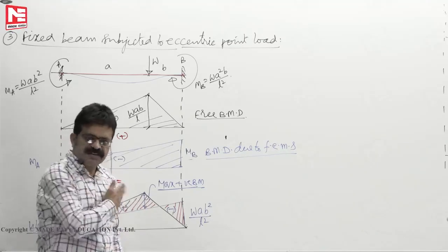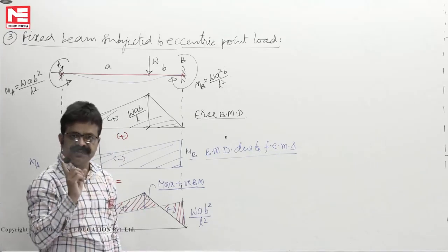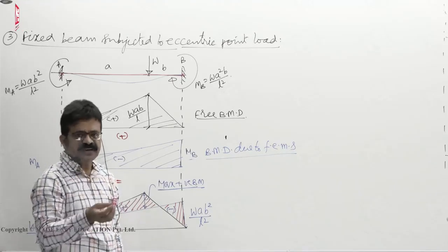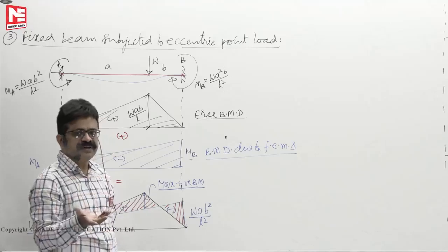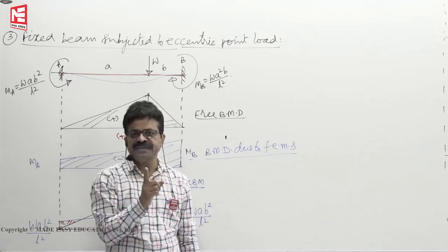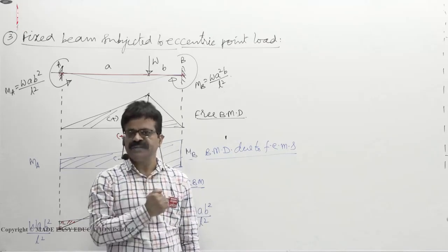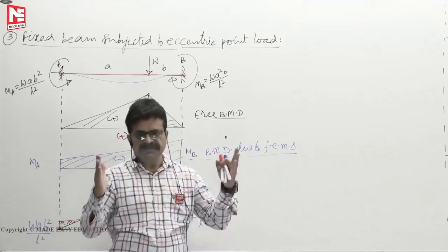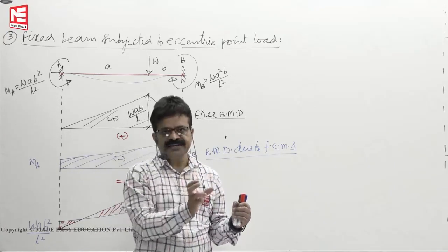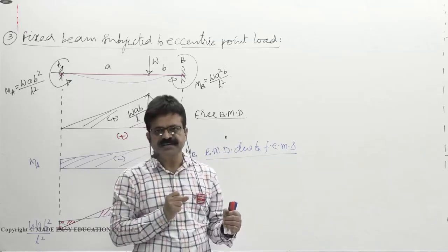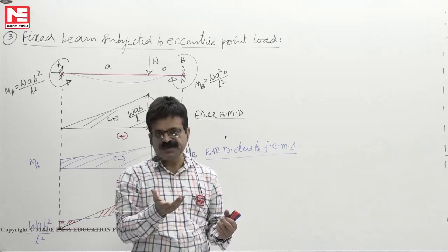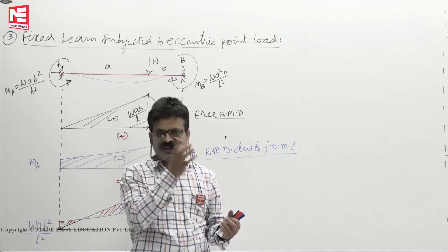In SM, all the problems that you have solved, ds is only 1. That's why in simple stress and strains or flitched beams or thin cylinders, wherever you take it, ds static indeterminacy is 1. So you have developed only one compatibility condition. You have a fixed beam subjected to axial load, say. What is the compatibility? Elongation in AC is equal to contraction in CB. Then flitched beams, ds is 1. That means static indeterminacy is 1. Then one compatibility, what you have taken?